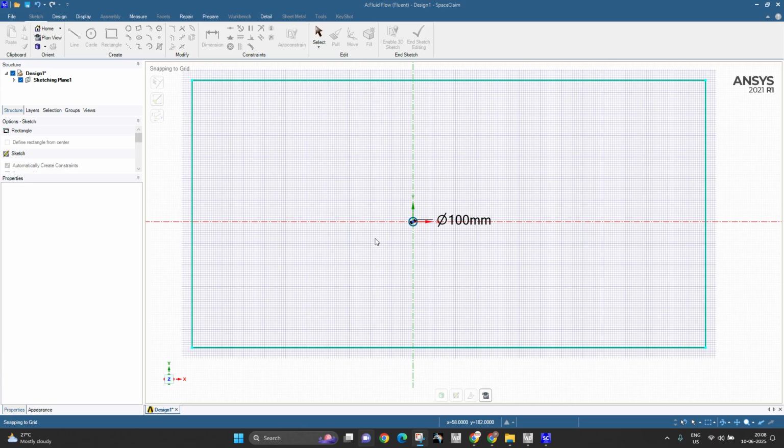The reason is, if a supersonic airflow is flowing upon a circle and shock waves are being formed, the shock waves are pretty huge by the way. They extend, and to check out the maximum length they can reach, I make sure the fluid domain size is quite big. Then only will I be able to track it down. That's why I make sure it is like this.